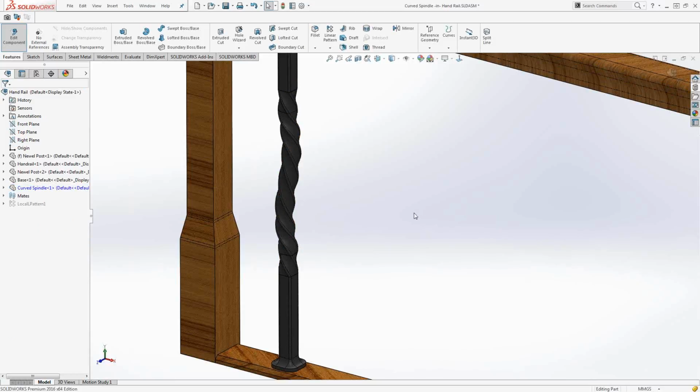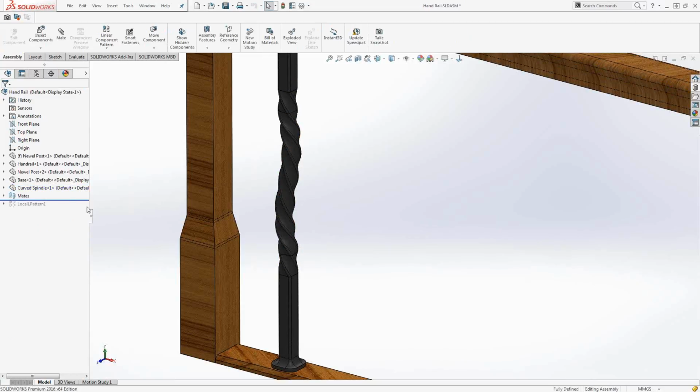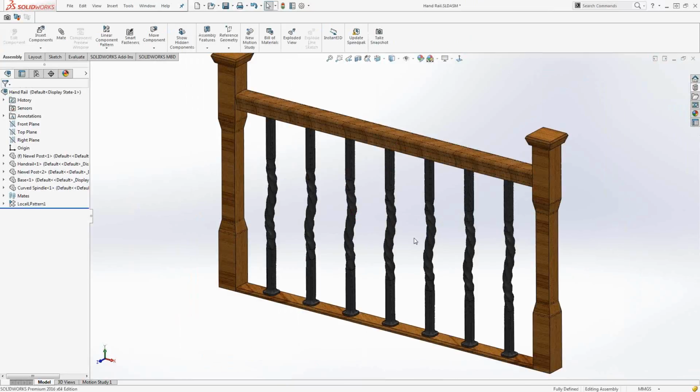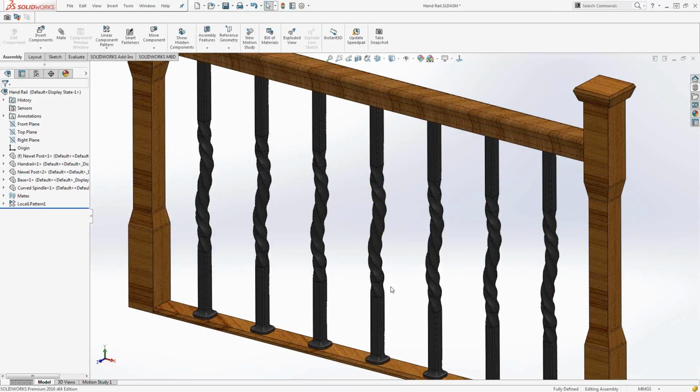All right. And when I exit out of my part, let me use my cool D key with the green checkbox that I just showed you before. Create a nice little linear pattern of this. Right? No need to create extraneous planes to get the job done. We can immediately start creating the sweeps the way we'd like them.